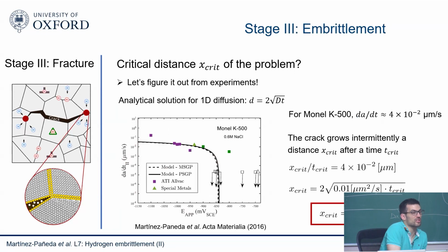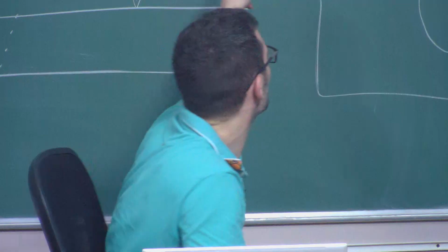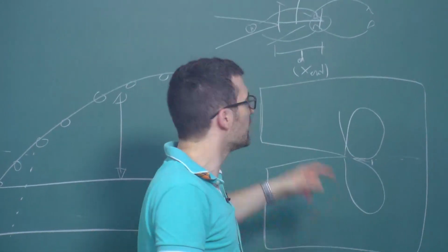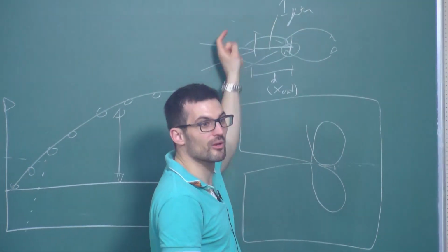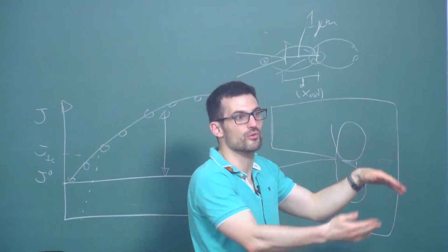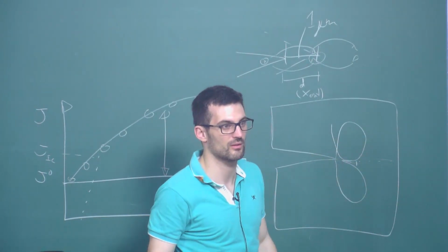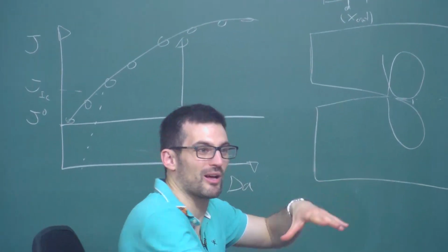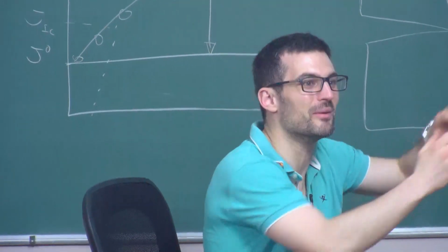You don't pre-charge your sample, so you're very dependent on the hydrogen coming from the environment. So it's environmentally assisted hydrogen fracture. That's why you see this very clear stage 2, where you need the hydrogen to diffuse. Otherwise, you don't get any fracture. So it's subcritical crack growth because your sample has not been embrittled in a way. It needs the hydrogen to come in and embrittle.